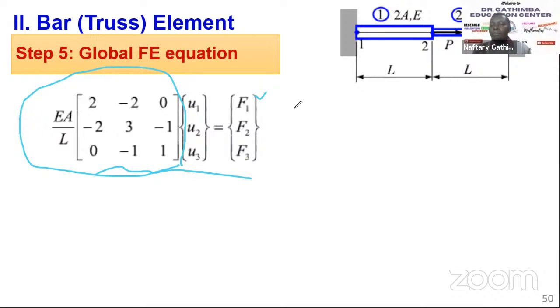But when we come now to solving the equation, you need to define the boundary condition. You cannot define a boundary condition on a single element unless it was a one-bar structure. If it was just one bar, fixed at one end, and I don't know whether the other end can be free or still fixed, this is still one element and at the same time a structure made of one element.